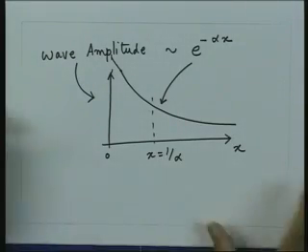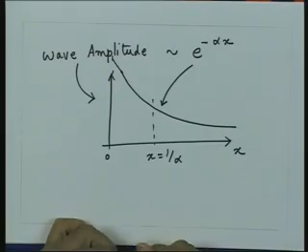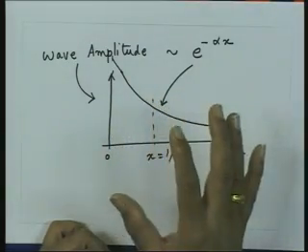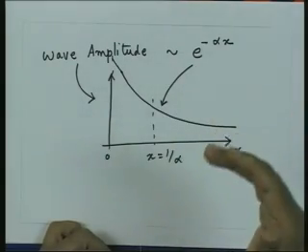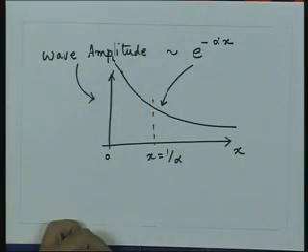What that means is that any electromagnetic wave cannot really go deeper into the conducting medium. Basically, it tries to penetrate a little bit from the surface of the conductor, or what that means is essentially the energy is in the dielectric medium. When this energy in the form of electromagnetic waves tries to go inside the conducting medium, it can penetrate only a short distance from the surface, and deeper into the conducting medium the fields are negligibly small. So, essentially this creates some kind of a surface phenomenon on the conducting surface.